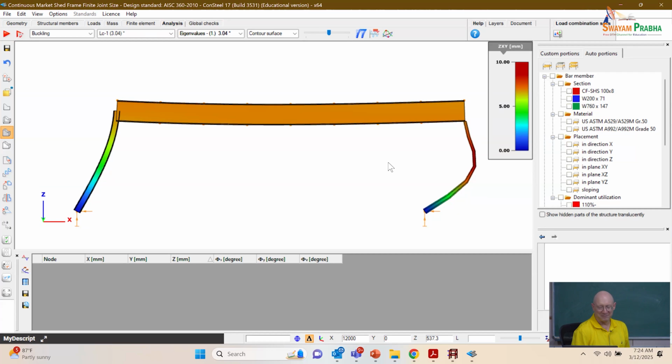Yeah, so it's kind of a hybrid buckling mode involving non-sway buckling of the HSS column, which has some partial restraint of side sway from the rest of the frame, but the rest of the frame is undergoing some sideways sway in this buckling mode. Right? And so the first thing I'd like to ask here is a question. I didn't write out a handout for this, but how many elements do we need to make sure we've got a good model of this HSS column?